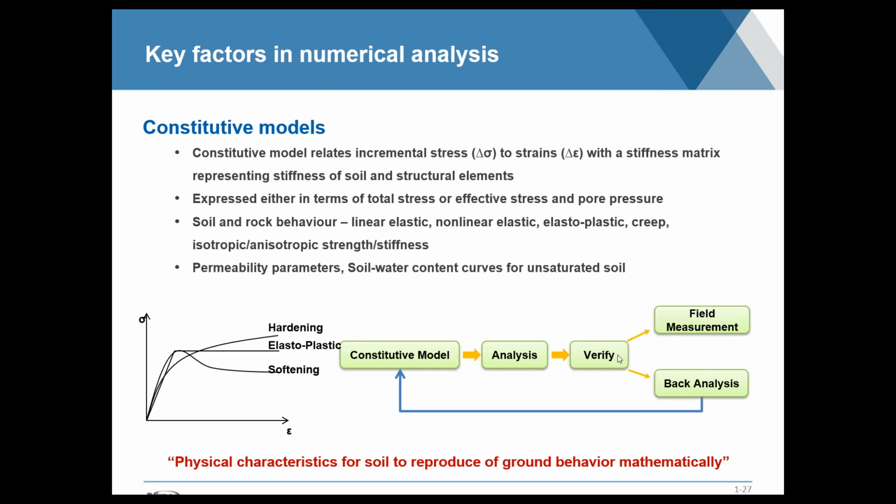And then you run the analysis, an iteration process, until you have an idea, either by having a range, like an upper limit and a lower limit of the behavior you're more or less seeing. And then, once the project starts, as you're progressing through the project and you start to get field measurements, you're again updating your model based on the field data that you have until you're much closer to what you're seeing in the field, and in that respect, calibrated your model.